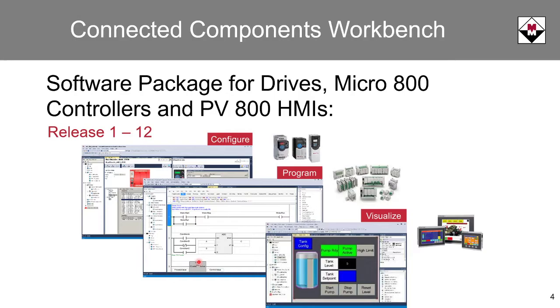Connected Components Workbench software is a free download right from the Rockwell Automation website. It is also used to configure PowerFlex drives and to program PanelView 800 HMIs. If you notice, there's a number of releases available. When looking at the software packages, you want to choose the version based on your Windows operating system requirements, the specific features available in that version, and the firmware that your controller requires.